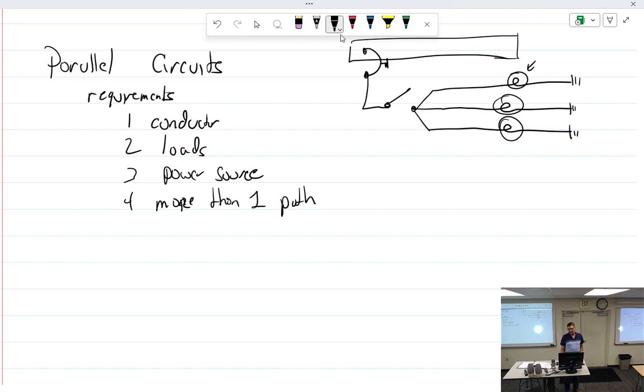But Evan said it's a bad ground. Well, it just so happens in life that little screw right out here that screws that wire to the airframe, that tends to be where you get corrosion, and a lot of times that happens.